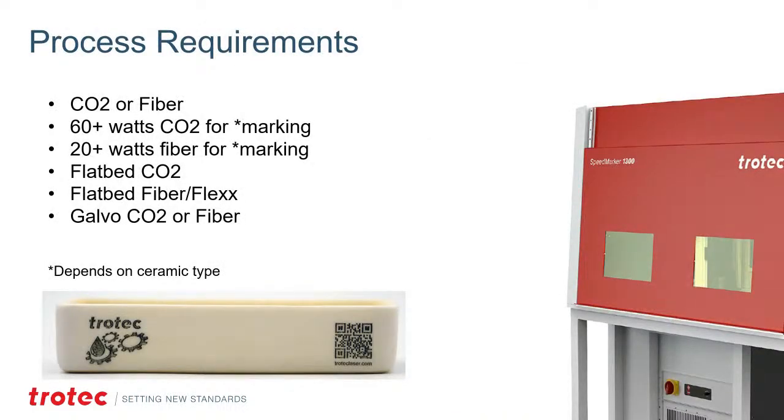So, process requirements. Typically CO2 or fiber, depending on the type of ceramic. 60 plus watts on CO2. It does take a lot of power to mark some, depending on the type of ceramic. As I explained, the different ceramics support different wattages and different types. 20-watt fiber laser at least for marking any of the ceramics that support fiber lasers. Flatbed CO2, flatbed fiber, or flex machine can be done with both CO2 or fiber on the Galvo system, depending on the ceramic type. So a lot of different options depending on the ceramic. And as I explained earlier in the previous slide, what ceramics work with what wavelength or type.